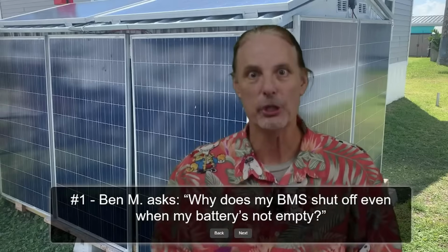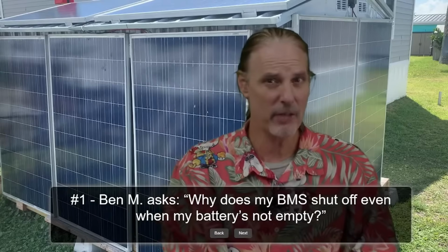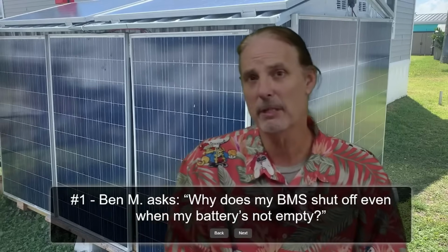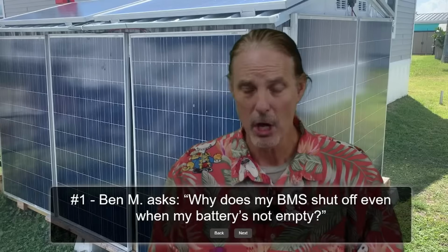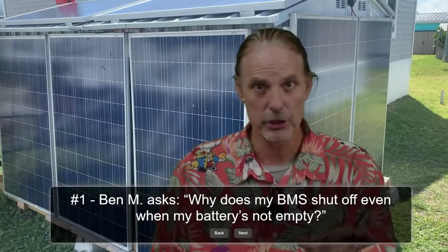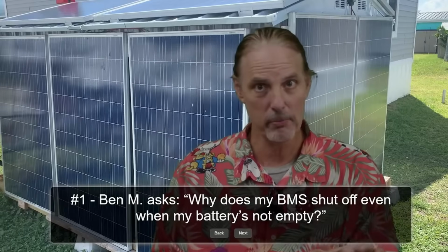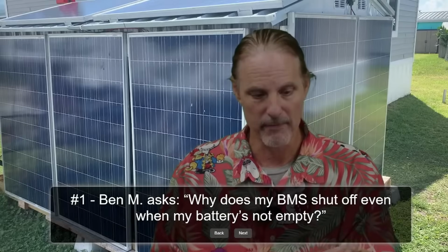And so that is why this BMS most likely is miscalibrated and reporting more energy going into that battery than it normally should. So a good way to calibrate this, and some batteries and some BMSs allow you to calibrate them, or you can go in with a voltmeter and determine the exact voltage, and you could use a very accurate voltmeter if you can, or use multiple voltmeters to get the appropriate value.